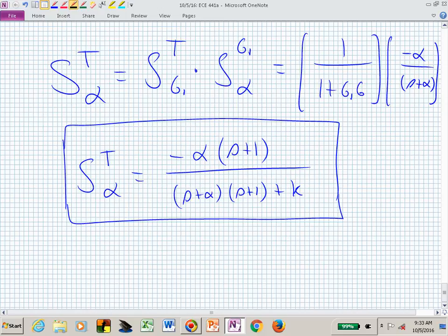It's strictly proper, which means at high frequencies, what's happening? S squared is dominating, isn't it? So we have S and S squared, so we have a 1 over S. What happens as frequency gets high? 1 over S. S gets big. This starts going down, doesn't it? It's getting small. We'll look at that after we do one more version of trying to compute this.